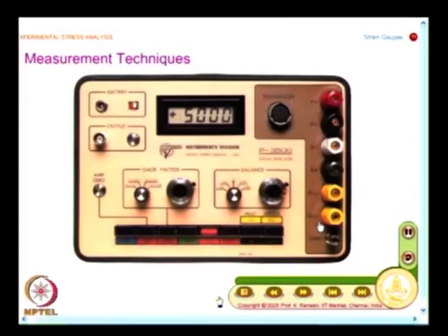So, one of the first steps that you will have to do is, have you selected the correct completion resistors of the Wheatstone bridge. The second aspect is, you have a knob available for setting the gauge factor, and you all know that delta R by R equals Sg into epsilon, and Sg is like a multiplication factor, and I said Sg is determined experimentally and supplied by the manufacturer. It is available with a percentage value of error. So, from batch to batch the Sg can change. So, you have to put in the appropriate value of Sg.